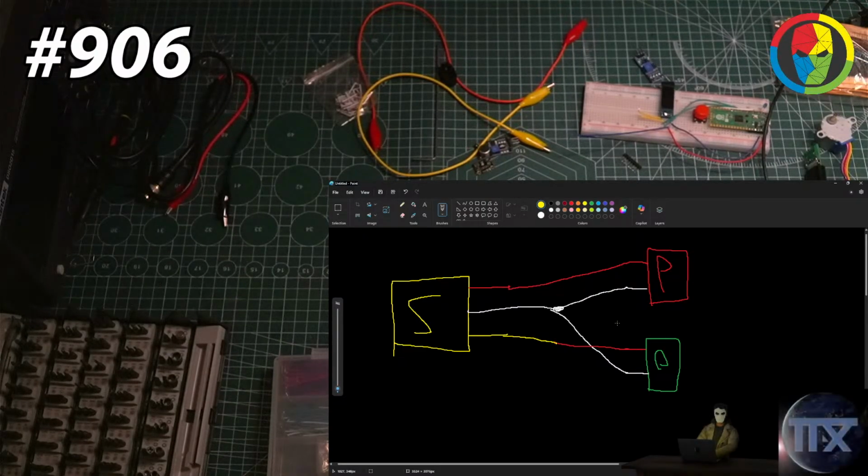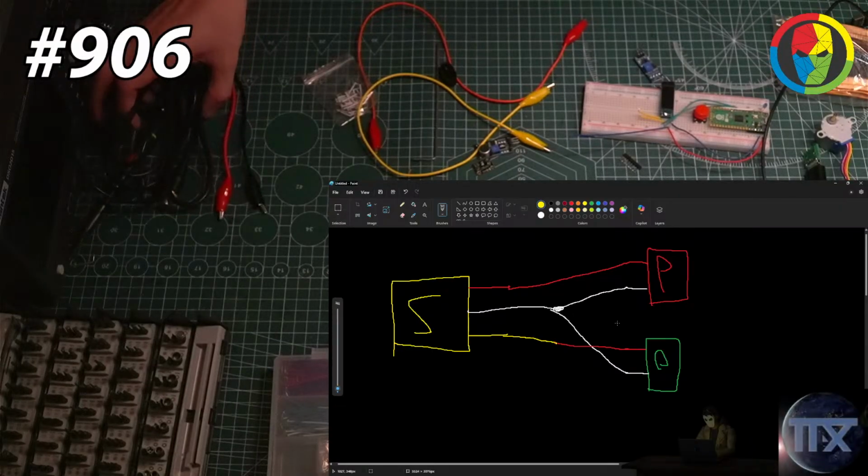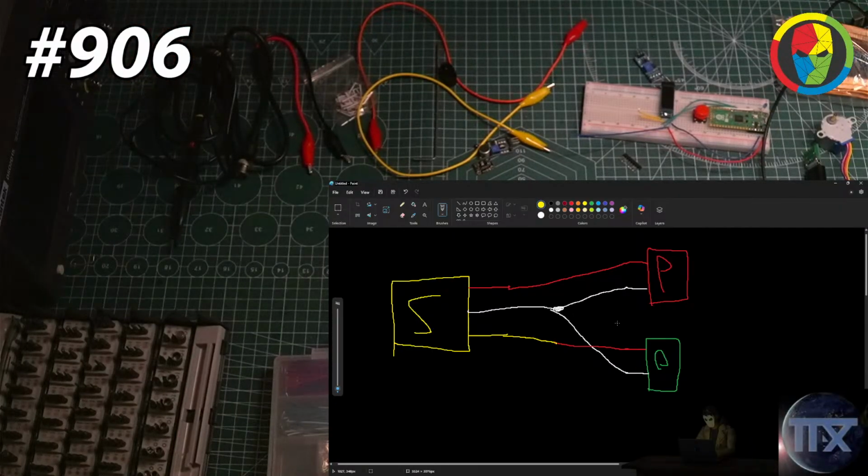Speaking of which, I actually didn't even know this. There are two types of ADCs on an ESP32, and channel 2 is always used to generate the Wi-Fi signal. So all of the ADC2 channel pins, when you're sending Wi-Fi, will be garbage. So it turns out it's not just that one pin. It's all ADC channel 2 pins on an ESP32.